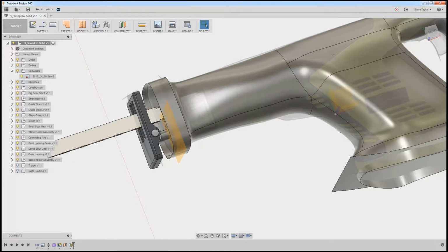For those of you who are Inventor users, you will have heard me mention Sculpt when referring to T-splines and to a workspace. In Inventor, there is a Sculpt tool that will allow me to take a series of surfaces, planes or faces, and combine them into a solid model. Fusion 360 has a tool that essentially works exactly the same way and is actually quite clever. This is a very simple model for us to work with. This tool is called Boundary Fill.